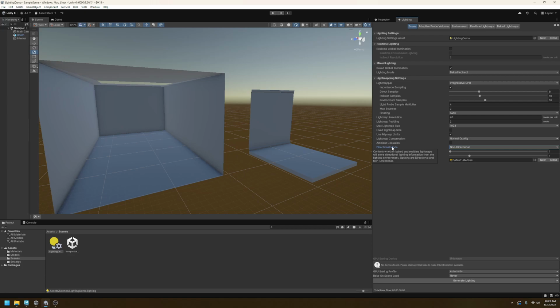They're only visible underneath directional lights, and this is supposed to fix that. But unless they've fixed it for Unreal 6, it minimally makes a difference, and it's not worth doing, as it adds extra bakes. So we're going to take that down. And that should be good for our basic setup. This is usually what I work with when I'm doing my lighting. And then when you're done, you can bump it up a little bit higher so that you can do your final bake when you feel that you're comfortable with this.